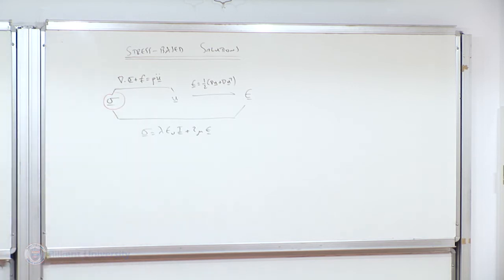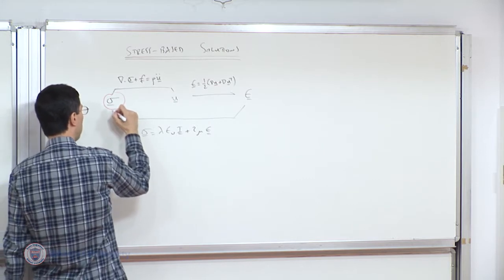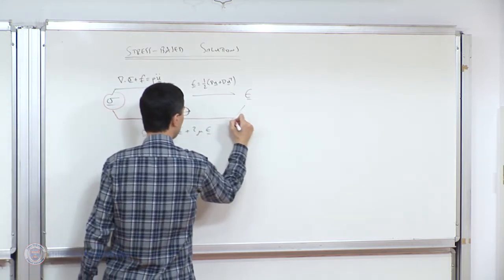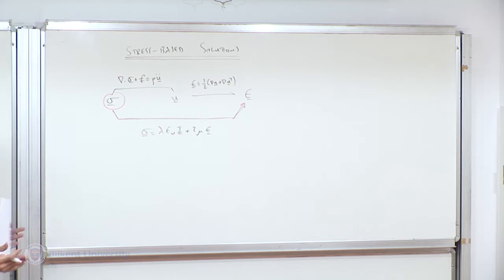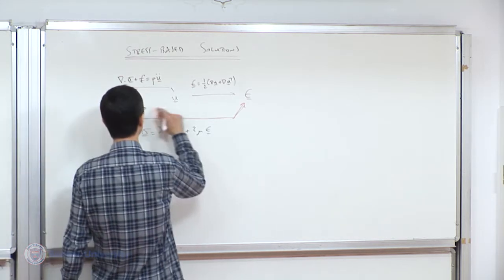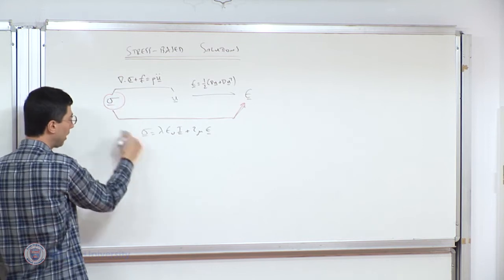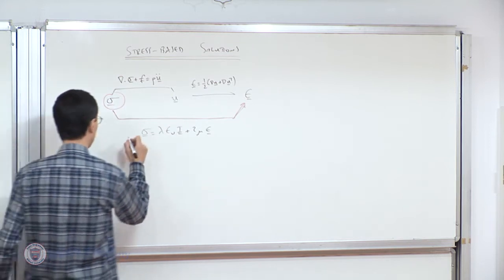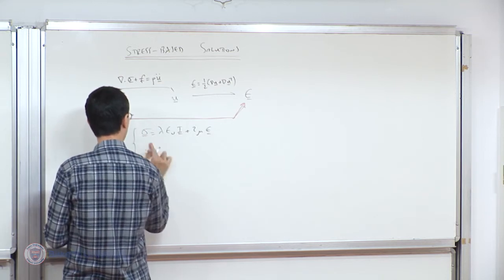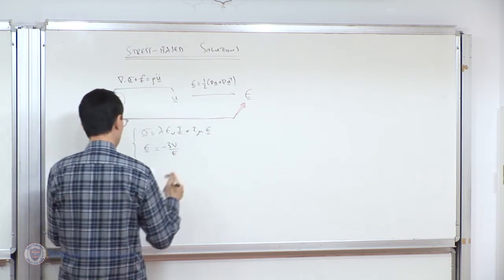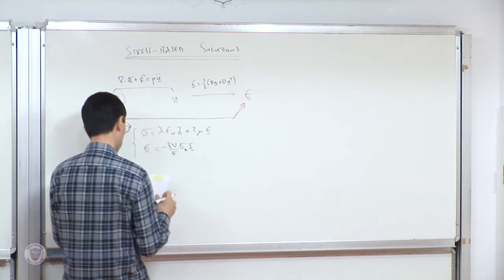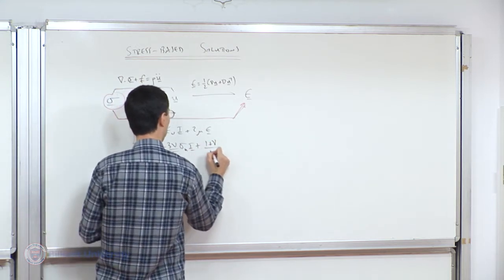Okay? I will start by proposing a form for the stress. Okay? Now, from the stress, then I will go and calculate the strain. All right? But, of course, I already know that for any proposal for the form of the stress, I can always invert this relationship to calculate the strain, right? So let me remind you, if I had given you the stress, then the strain is 3 nu over E, sigma_H, the hydrostatic stress, times the identity, plus (1 plus nu) over E, sigma.